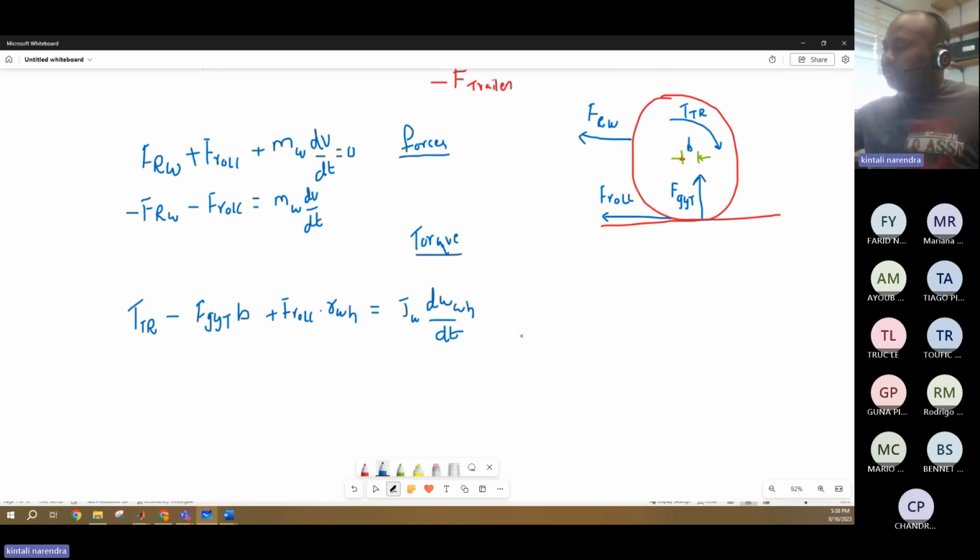In this equation, you put all the moments and equate them to the torque. Everything is torque, right? Force into radius, and here also it is your polar moment of inertia times the angular acceleration. That's what you put there, right? Yeah, inertia into angular acceleration. Okay, got it.